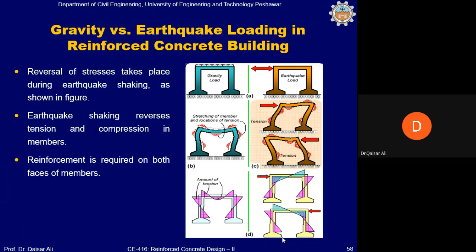Whatever pre-stress force is lost due to creep is basically lost capacity of the member. So creep is important in pre-stressed concrete. It must be controlled, or at least known to us before we design our pre-stressed members. However, in reinforced concrete, it is not of such significance.